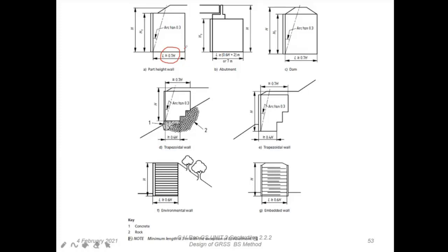Now for our analysis, of course, a plane stress condition like a retaining wall, the point we are trying to make is this is a reinforced soil mass. So what is it there now? We got all the reinforcement within the body. We still don't know the size and everything else, spacing, nothing we know. But we know that we are going to reinforce it, and so it is going to act like a single composite mass now.